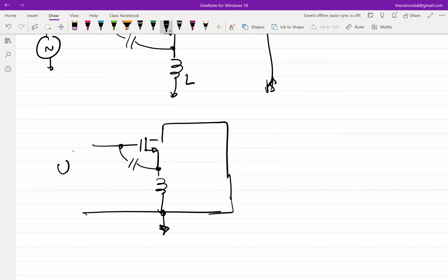So I apply a V, then I have to find out I. This I clearly goes through the capacitor, right? Because this capacitor, by the way, anyway exists because it's a CGS. So it develops a VGS of I by j omega CGS, right?